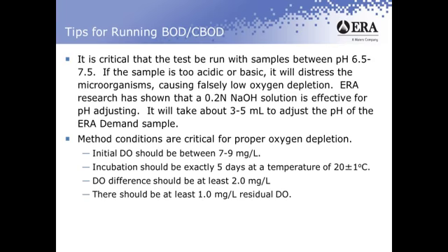When you're doing the incubation, make sure that you provide an air barrier on those BOD bottles to not allow any air to enter the sample during incubation. If you allow air to enter during the incubation period, you're going to be adding oxygen to the sample and you will get falsely low results.